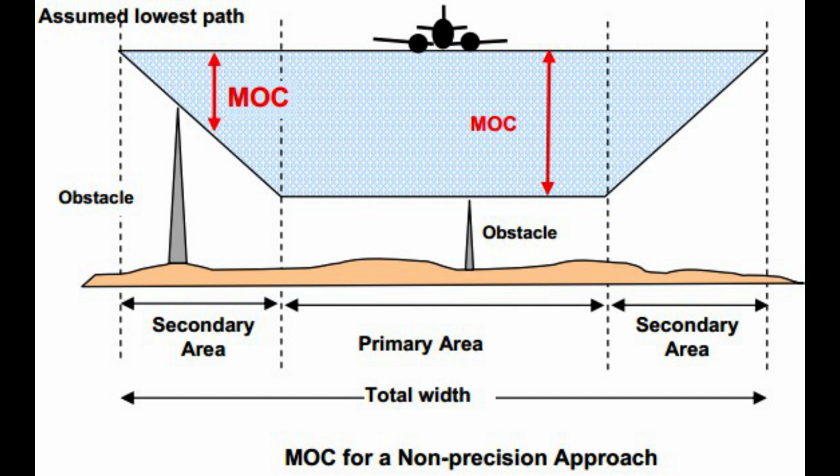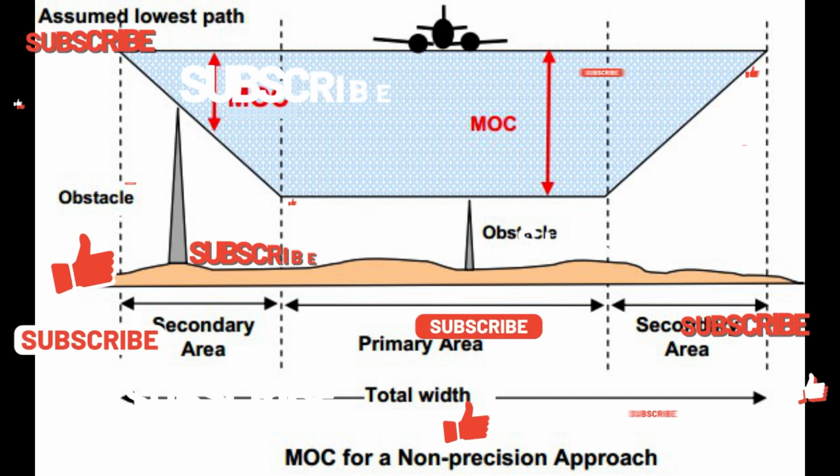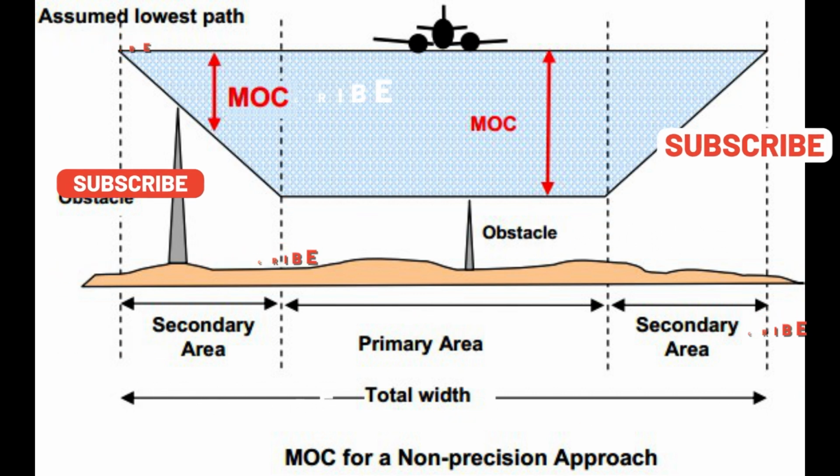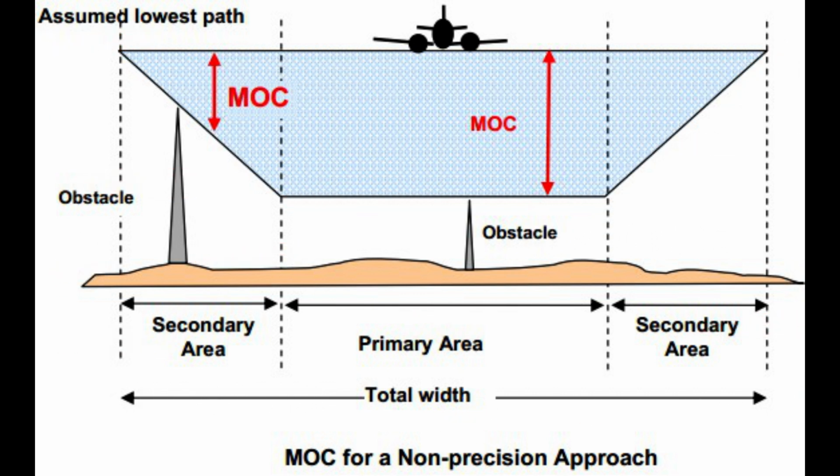The primary and secondary area obstacle clearance criteria, airway and route widths, and the ATC separation procedures for en route segments are a function of safety and practicality in flight procedures. These flight procedures are dependent upon the pilot, the aircraft, and the navigation system being used, resulting in a total VOR system accuracy factor along with an associated probability factor. End of page 2-18.